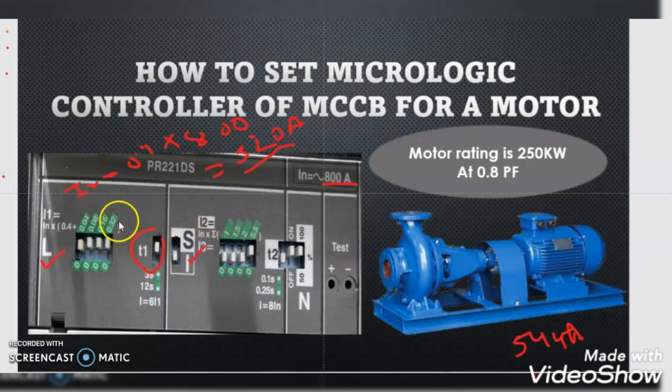Let us take another case to have a better understanding of the importance of the Micrologic controller. Suppose you set the I1 setting and I2 setting very correctly, but your T1 setting is wrong, meaning your motor has a starting current lasting 6 seconds, but you set the T1 setting at 3 seconds. Then what will happen?